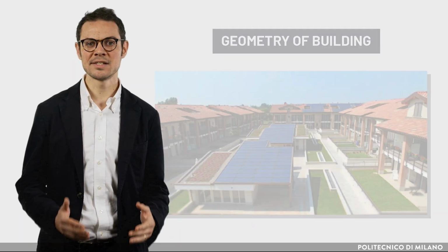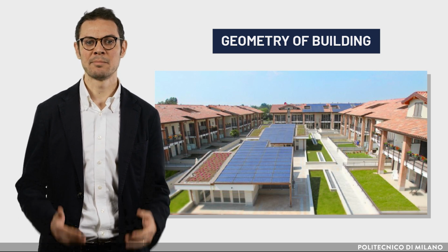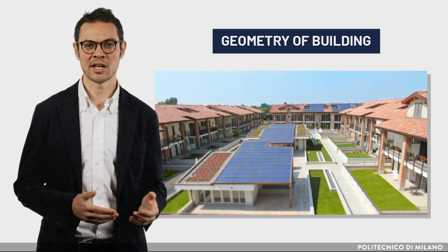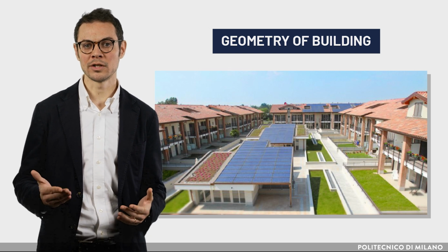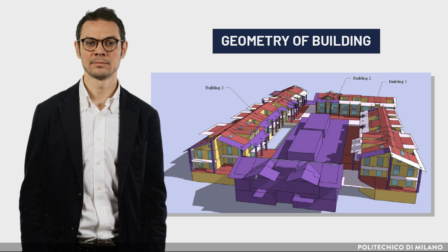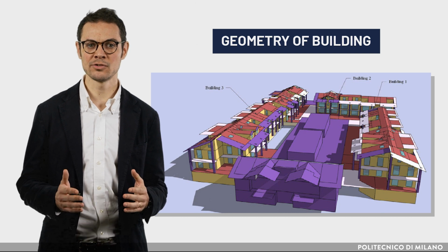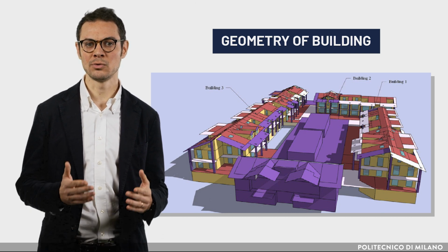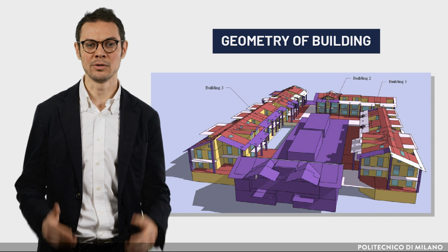First of all, according to the features and complexity of the buildings, several simplifications have to be introduced. These represent uncertainties to take into account in the interpretation of the results. Some elements of the architectural language, such as basement, columns, frame, portals, and cornices, can often be overlooked to reduce the computation time. However, the user must be aware that the excess of simplification can unintentionally lead to underestimating thermal bridging effect, whose magnitude may not be negligible.